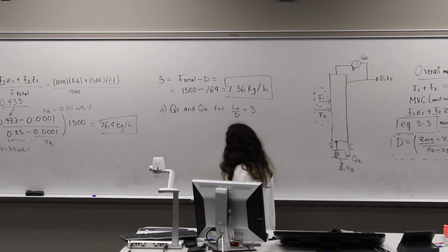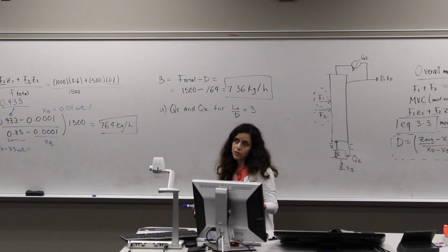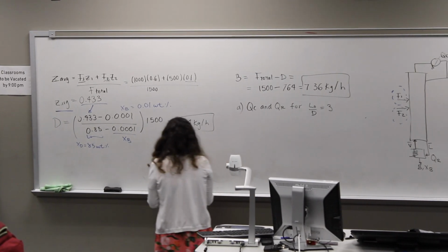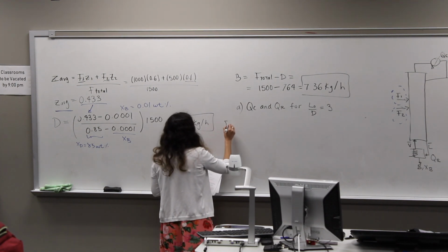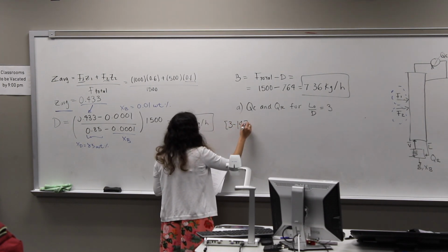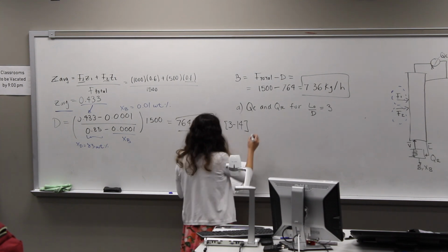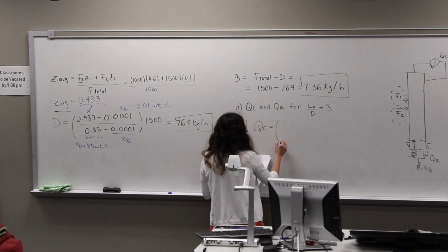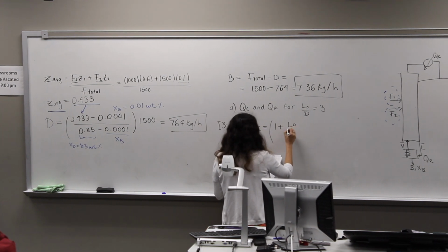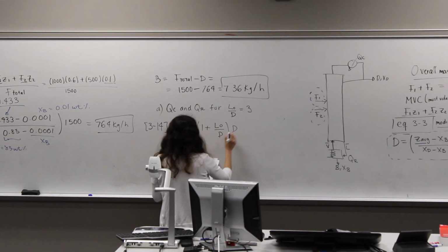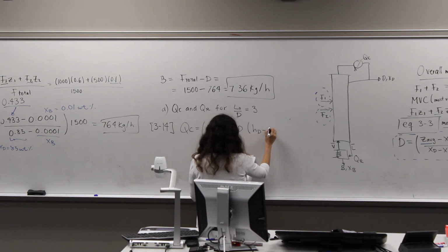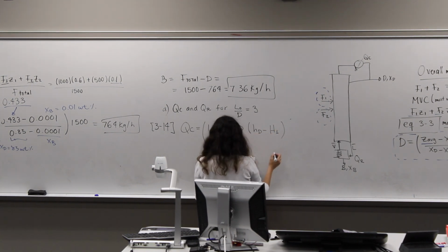I guess. So how we can find heat loss? With the energy balances, right? So we need to go back to our equations for energy balances for our column. And one of those equations is equation 314. Well, we know that the heating load for the condenser is 1 plus L over D, D, HD, HI, so the enthalpy differences.